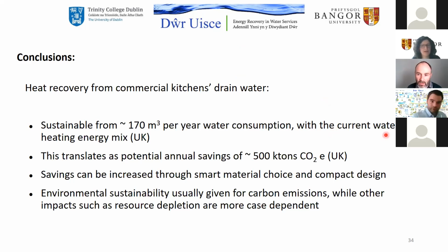Isabel, just a comment while I'm giving a moment for everyone, if there are any questions being formulated. You note here 170 cubic meters per year consumption. Earlier Jan mentioned about 2 cubic meters a day was the kind of threshold. So really, 80 or 90 days per year at 2 cubic meters per day makes it sustainable. So it's very much a feasible option to make it sustainable for a year as well, which is great.